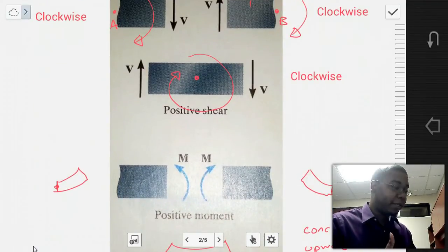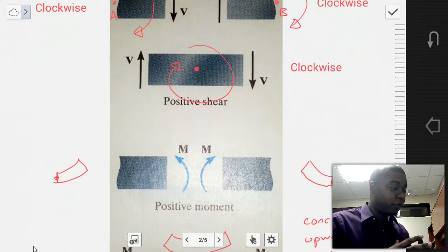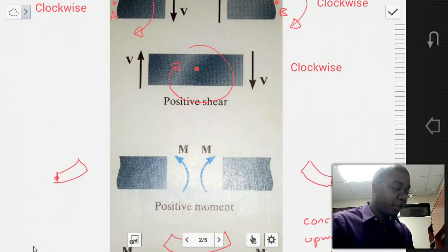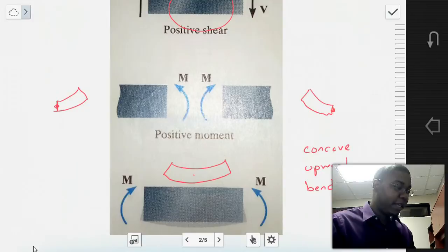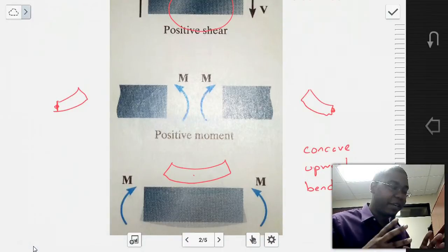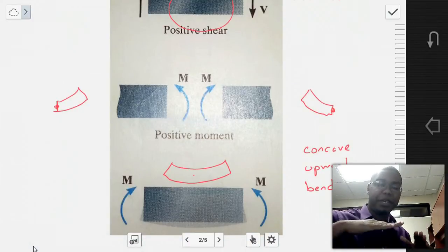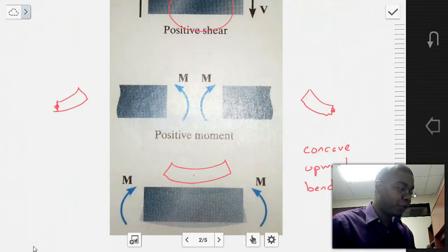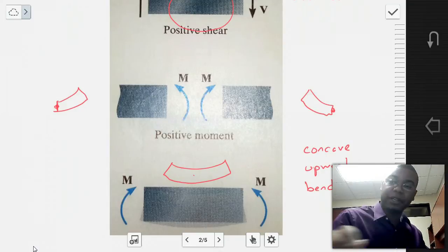Well, let's look at a beam. Let's do the method of sections, and let's put that internal moment that develops in the beam. The moment is positive if it would create a concave upward beam. If the beam was to bend concave upwardly, then we have a positive moment, right? So notice the left-hand side, we have a counterclockwise sense, right? So the moment is for the left-hand side of this diagram.